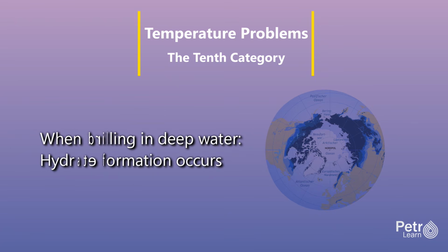Hydrate formation occurs when drilling in deep water where cold temperatures and high pressures cause water and gas to combine into ice-like solids that can plug the BOP or flow lines. Methanol or glycol must be used to prevent hydrate formation.